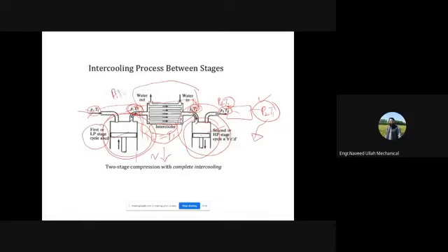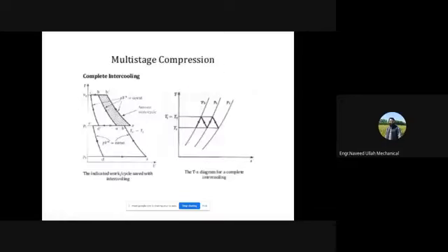And Ti here, so before intercooling or intercooler, after intercooler if you have PI but T1, okay, so this means what you have done is T1 is this one. This is called complete intercooling. I think I have shown this on the TS diagram also, okay. The ultimate pressure is P2 by P1, so P1 to Pi, then intercooling, complete intercooling, what is this? This is T1, this is Ti, right?